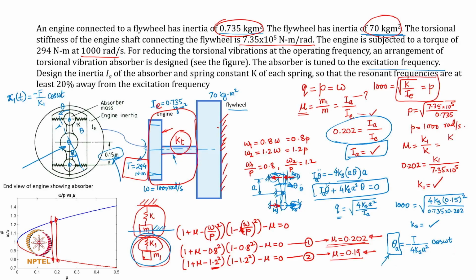When these springs are in action, theta A into A will be the total stretch in the springs, and that will also help you find out that if this engine is operating at that speed for maybe 5 years, whether the springs will have enough endurance to sustain so many oscillations or not. All of these are basically the implications of this vibration on the design robustness.